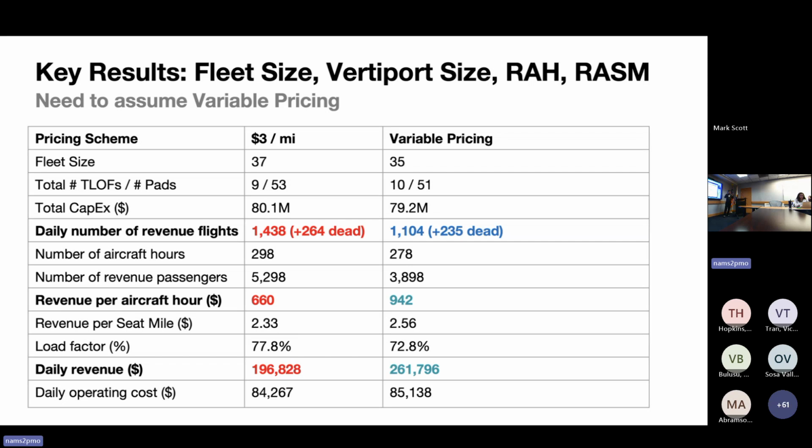Right, and we use a probabilistic mode choice model, that's calibrated, where the traveler looks at the cost of taking an Uber, the time of an Uber, the cost of that time, the cost of taking this eVTOL at the price that I've set. The first and last mile cost is taken into account, the first and last mile time is taken into account, the flight time, the transition time. All that's taken into account, and it makes a probabilistic choice, using the conventional methods used in travel demand modeling, what's called a logit choice model.